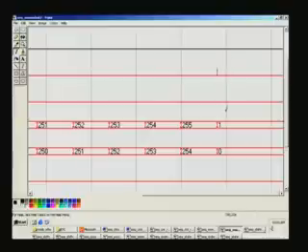But you said momentarily it's 255, right? Yes. Momentarily. Is it not supposed to be reflected there? Here. So it is so fast it is happening, right. So because the moment it goes to 255, and perhaps let us examine after back annotation, let us see whether that shows up. You are right, that is a point we can examine later on, right. Right now we can't because the simulator does not contribute to the gate delays. That is why I said instead of 50 megahertz which is shown here, suppose I make it 2 gigahertz or even more, this will still show up, and unfortunately many people have jumped to conclusion based on mere simulation.